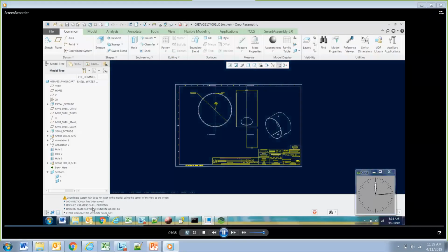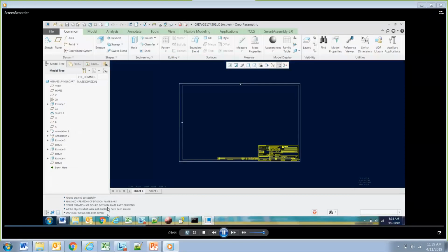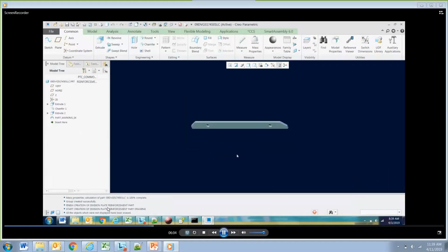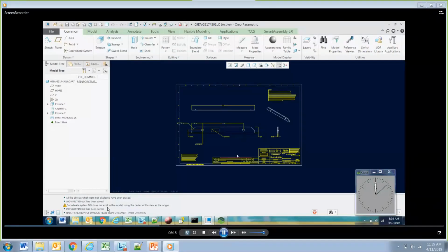It found some other parts that already existed in Windchill. They must have been shared between different past configurations, and as a result, they didn't get created because it said, hey, this is already in Windchill, I don't need to create this. Part of the reason it's finding parts up front is that we had already run the 2-pass configuration before we ran the 3-pass configuration through this tool, and some of the parts are indeed shared. We'll see this in a moment as it starts to look for nozzle parts, because absolutely all of the nozzle parts are shared between both 2- and 3-pass configurations.